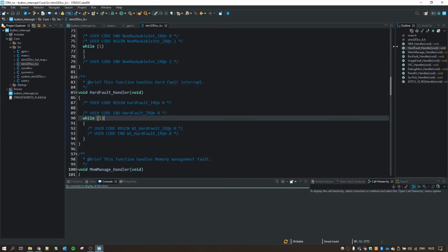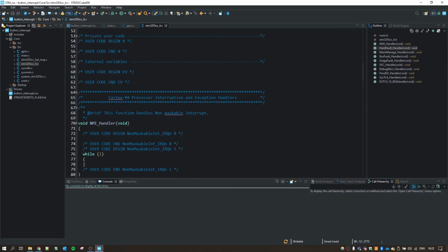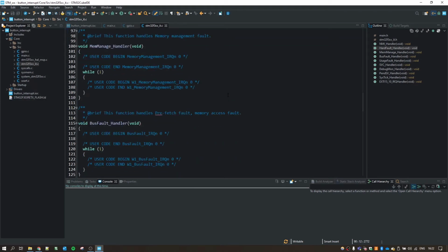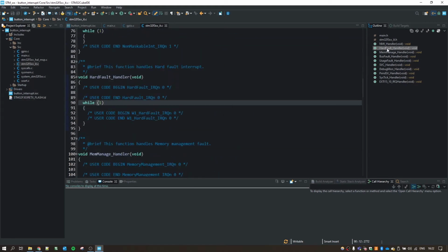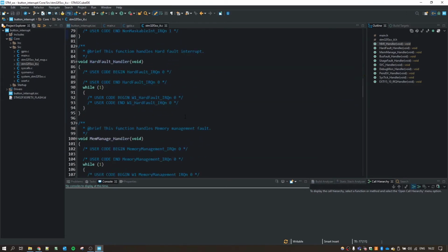Okay, here we go. And now, as you can see, these are all the interrupts which are already configured for you, because these are some serious interrupts like a hard fault interrupt and an NMI handler, which is a non-maskable interrupt. Again, all these things are out of scope of this video, and like I mentioned, interrupts is really an involved and a broad topic, and we are only talking about GPIO interrupts in this video to begin with, especially.